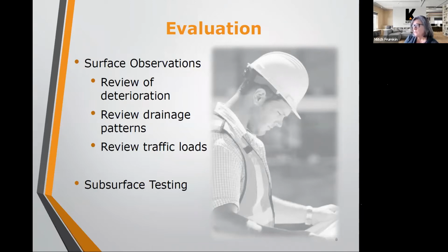Depending on what the issues are in the community, we may also request that the coring contractor perform an informal percolation test in the open core hole to see if there is adequate drainage. If there is standing water beneath asphalt, there are certain techniques we can use to alleviate that situation so that you get a longer life out of your pavement.